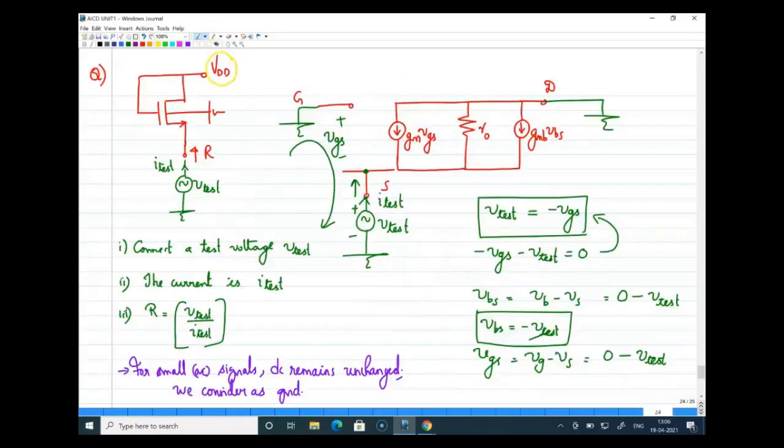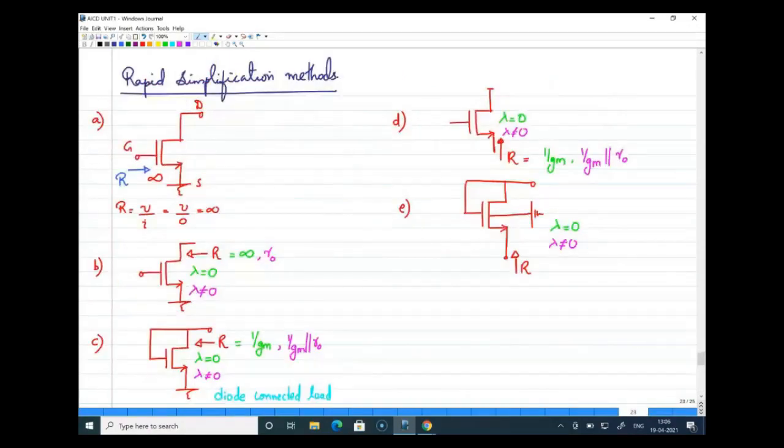So we started our discussion here, and we had the same thing at point A as an example in C. There it is 1 by gm parallel to R naught. Now without lambda I can say it is 1 by gm plus gmb, and with lambda it is 1 by gm plus gmb parallel to R naught. Now, even without doing this analysis, you can say this straightforward,